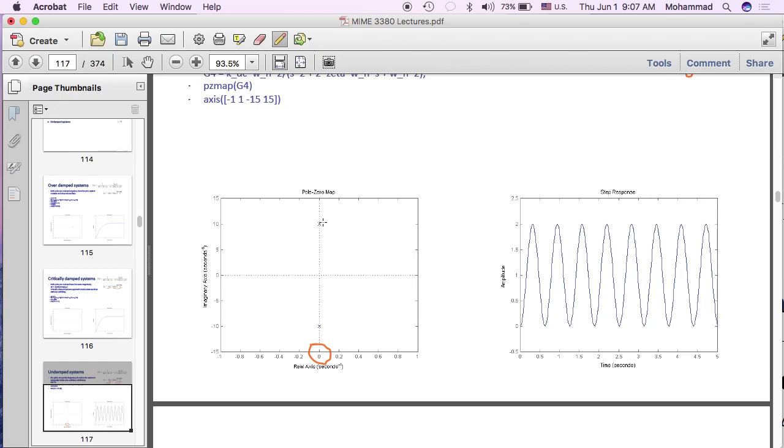And if you look at the step response, this is the typical undamped response. So it's pure oscillation. It just keeps repeating the response without any energy loss. So zeta being equal to 0 means what is the value of damping? 0. An undamped system means there is no energy dissipation, no damper. That's why the system will basically oscillate forever.